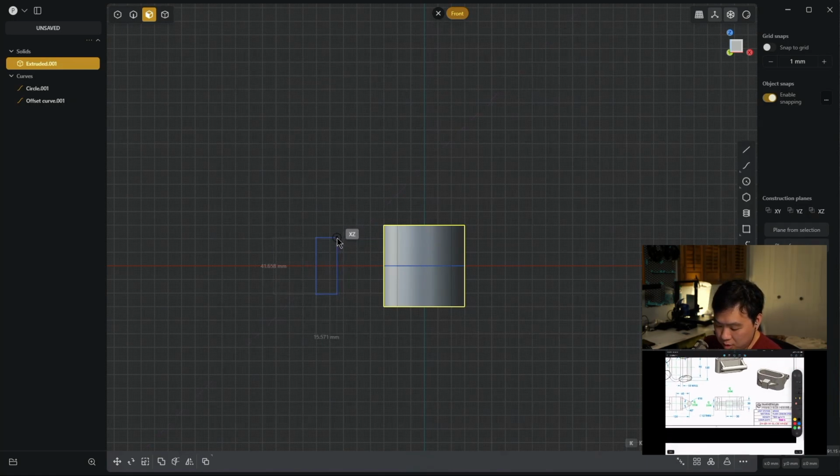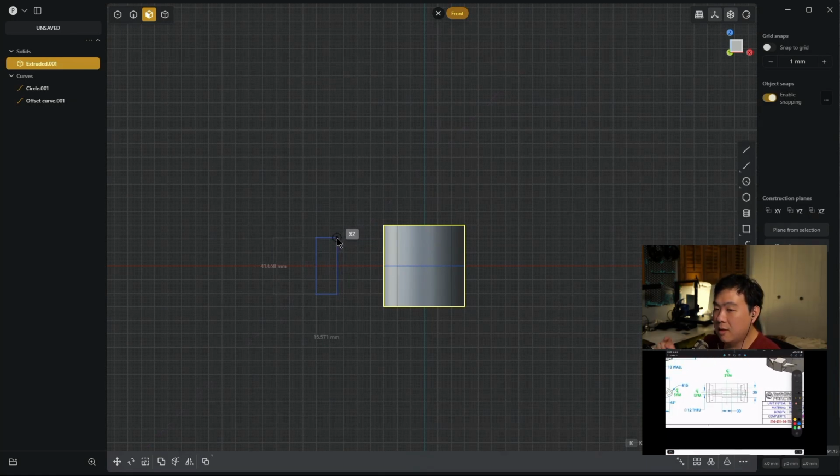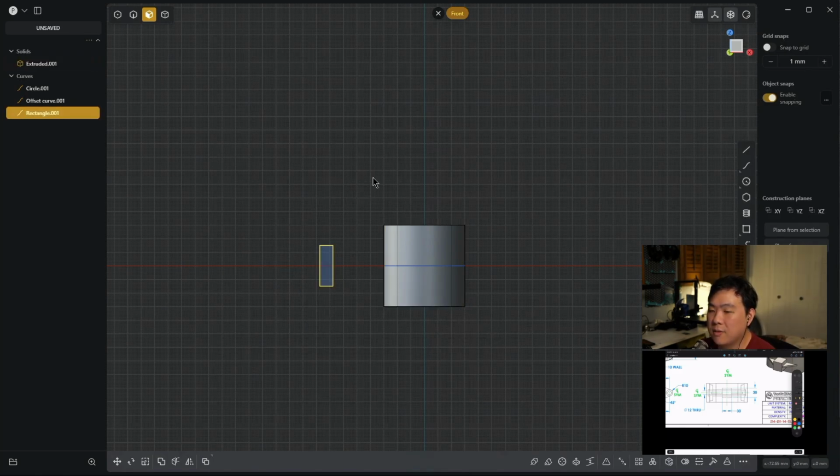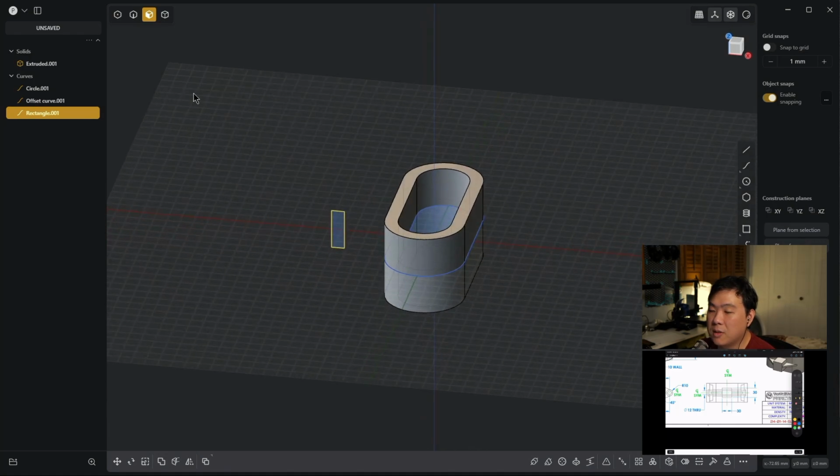We know from our drawing over here, so I guess the height is 30, and we know that the depth is 30, but what we don't know is the distance from the front of this base to the front of this left side. But we don't need to know that immediately. All I'm going to do right here is enter in 30 for the height, and then press enter, and leave it as this little kind of sliver. We know that the depth is 30.